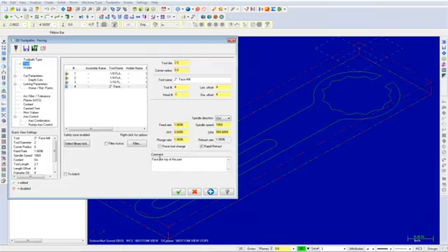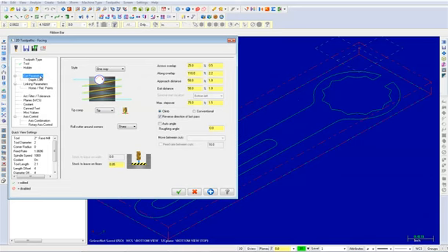Once complete, choose the cut parameters. Make all the necessary changes as shown. Change the style to zigzag. Also, make sure the amount to leave on both the stock and walls is set to 0. For move between cuts, ensure that it is set to high-speed loops.